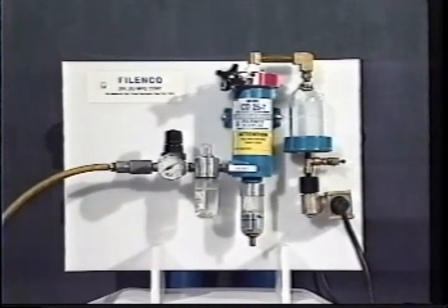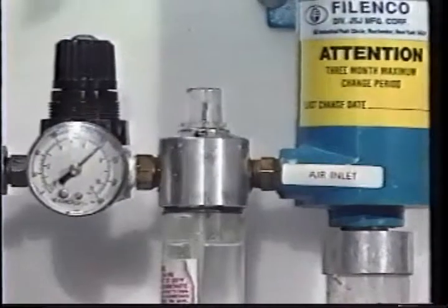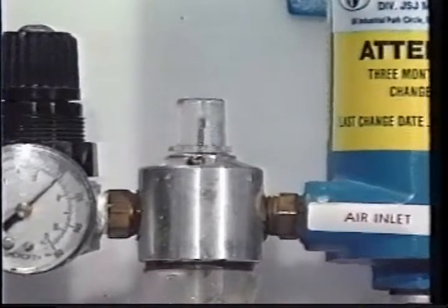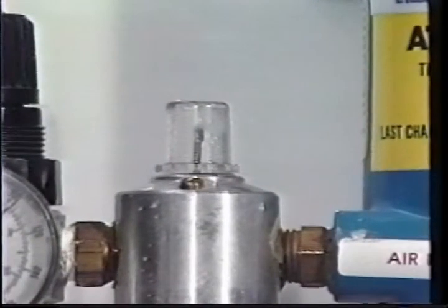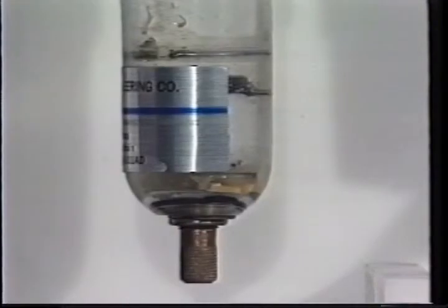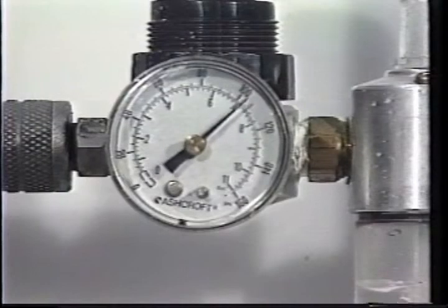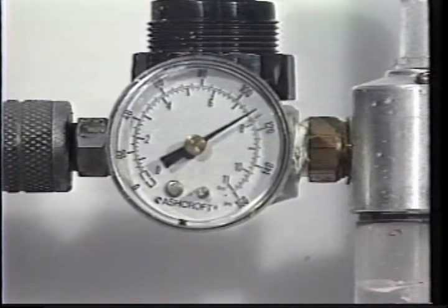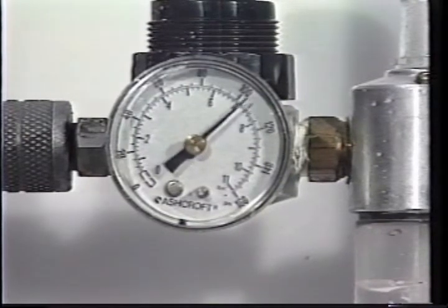Used mainly in OEM applications, it is rated for 7 SCFM at 100 psig. Moisture is introduced into the air by a lubricator at a rate of 1 drop per second. The condensed water flows into the separation section and drops into a piston-activated drain, specifically designed for this small unit. Pressure swings caused by interrupted airflow from an intermittent operating solenoid activate the piston drain to discharge condensed liquid.